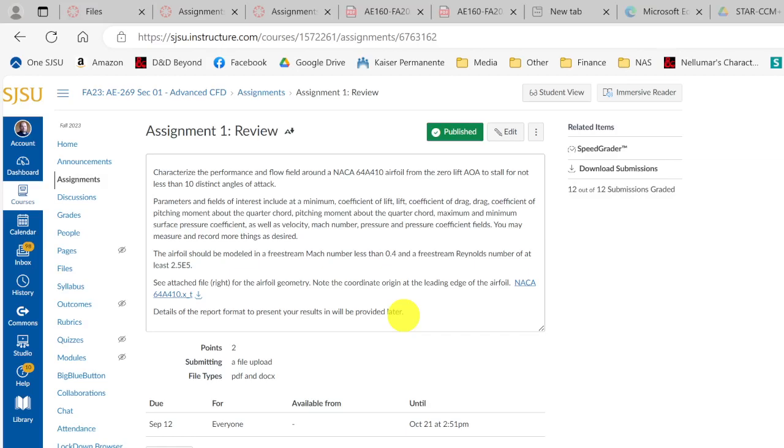Right, you think that. Nose down would be positive. Yeah, airfoils use a different nomenclature. For anything concerning airfoils, nose up is a positive pitching moment, nose down is negative. So I suspect that might just be flipped in your case.